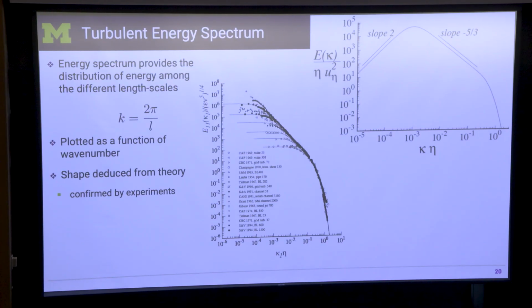So this is considered a proof that the Kolmogorov hypothesis can be reliably used for our purposes. But what you need to know is the top right plot. There's a minus 5/3 slope in the inertial range, which is between the dominant L0 and the viscous dissipation range. So that minus 5/3 slope is very critical. This is how LES becomes viable for many applications. Okay? So you get a minus 5/3 slope.